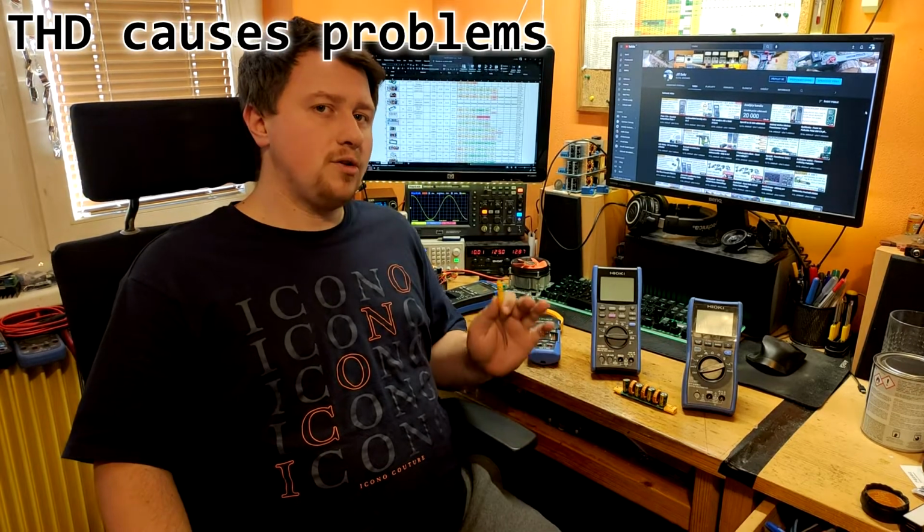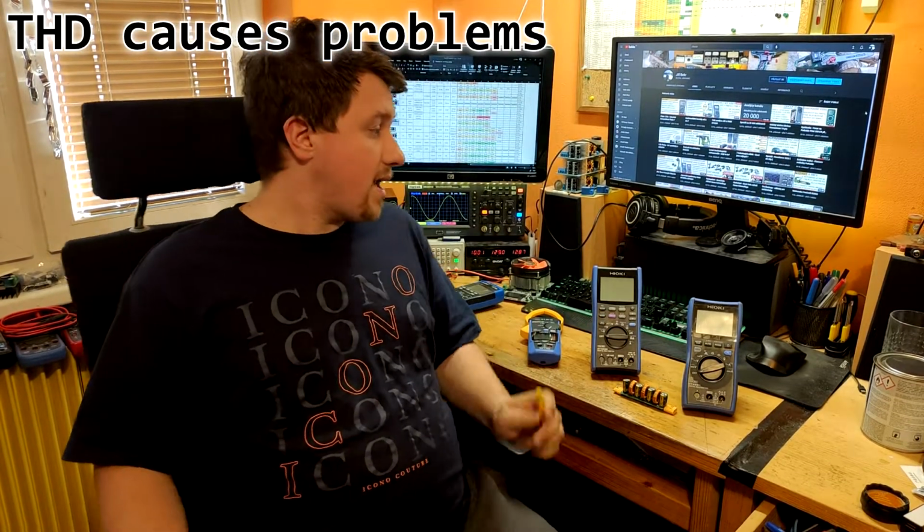Higher distortion will cause problems. For example, my FSP twin battery UPS is constantly monitoring the network, and if someone uses a hairdryer with thyristor regulation, the UPS actually triggers. I have my doubts that the hairdryer would pass regulations regarding EMC here.